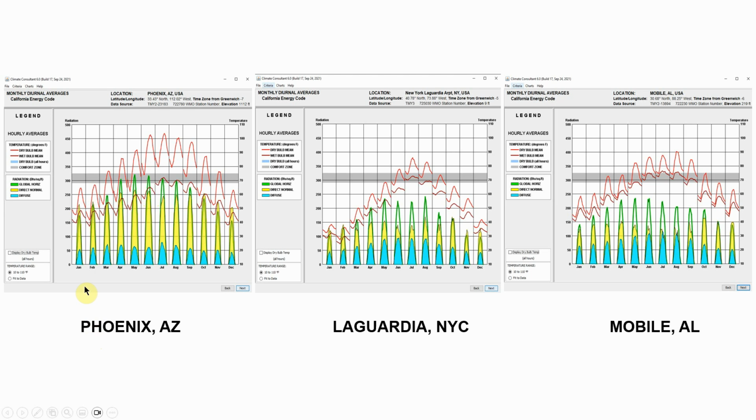But also you'll see, so why in January here is our direct normal more than the global horizontal? That's because the sun is at a pretty big angle to the surface that we're measuring. In this case, this is the ground, and so because the cosine of that angle is larger, it means that the actual global horizontal, which is the direct normal times the cosine plus the diffuse, will be lower than the actual amount of direct normal coming in.